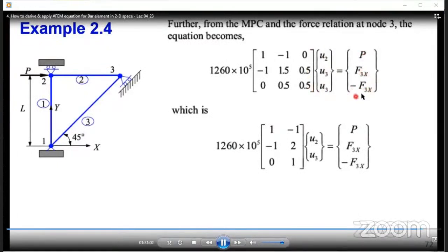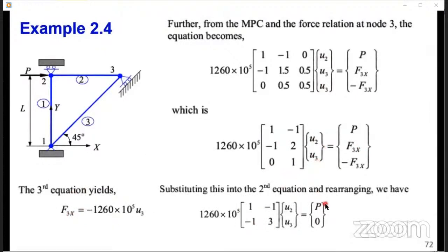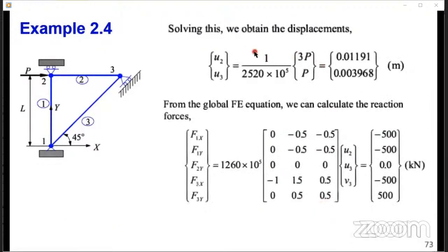So you see how it simplifies your work, right? And your equation, you can be able to solve. Now you no longer have 3 unknowns, you just have 2 unknowns. And this is what we condensed here. And doing so, you can solve for F3 and the forces and the reactions. I've shown that. So everything can be solved in very simple terms using those conditions.